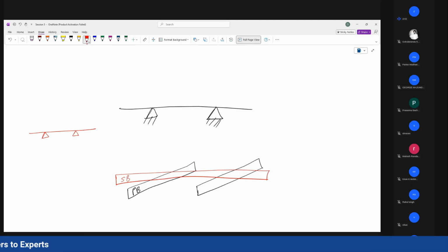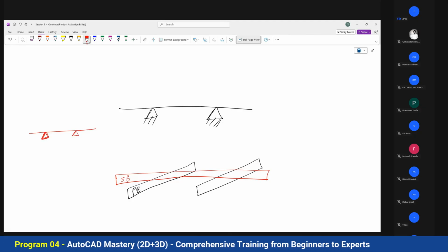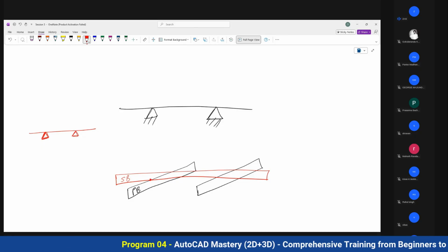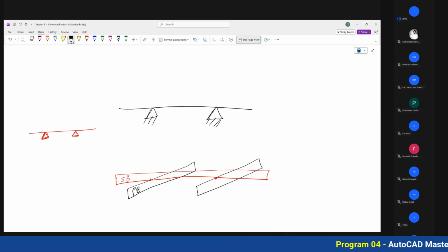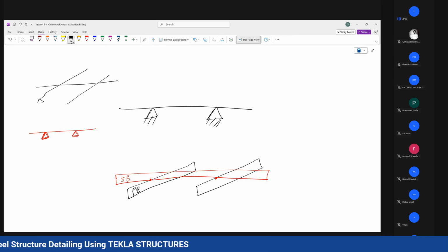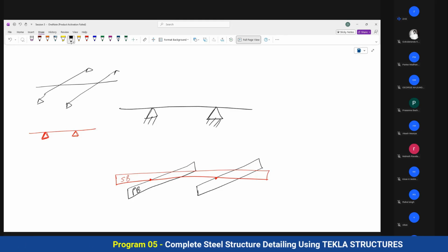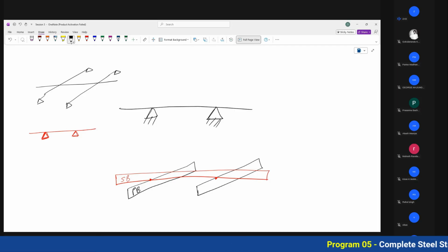For secondary beams, the support condition you can apply as this pin support. If you want to model this separately, then wherever it is touching this part, and this part, you can assign as pin support. But if you want to model this whole thing in STAAD.PRO, then you can directly model it like this. You can model this 3D element in STAAD.PRO like this, and maybe your primary beam is supported here. Primary beam might be supported somewhere. So give this kind of support arrangement and apply and run the model. It will work fine.